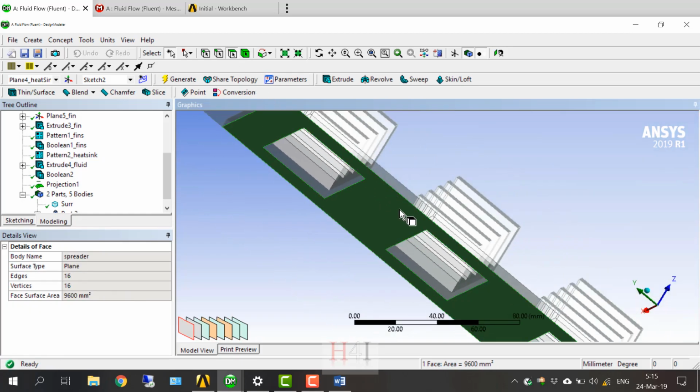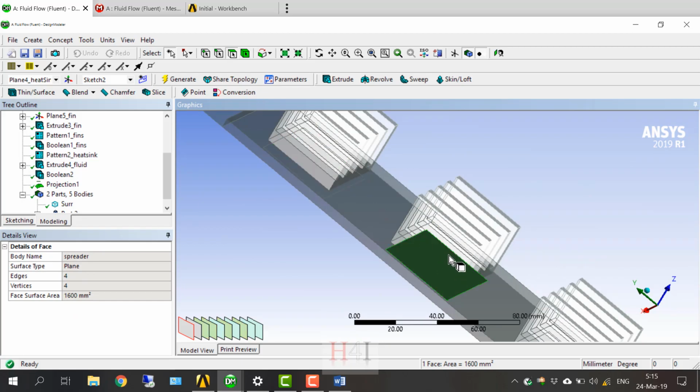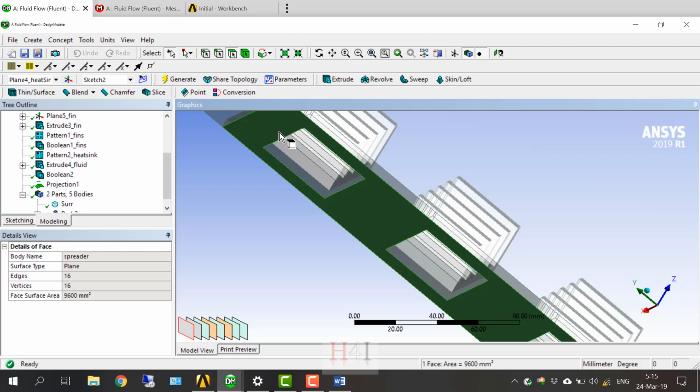If you know how you calculate the heat flux for each thermoelectric generator, right? Yes, I have an equation for the heat flux for each thermoelectric generator. You use the spreader as a face, and in Fluent you use the boundary condition to calculate the flux. No, the heat spreader is adiabatic. This surface has no flux at all.